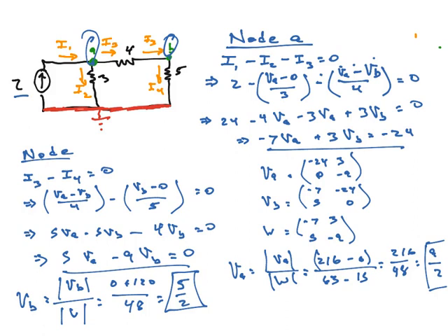And this was nodal analysis. Same steps as the other one, only here I had 2 nodes to worry about instead of just 1. And so we had the extra bit of algebra at the end. The physics of it goes like this. You're given a circuit, you choose a ground. Once you've chosen a ground, you label your nodes. For each node, label the currents coming in and the currents going out.